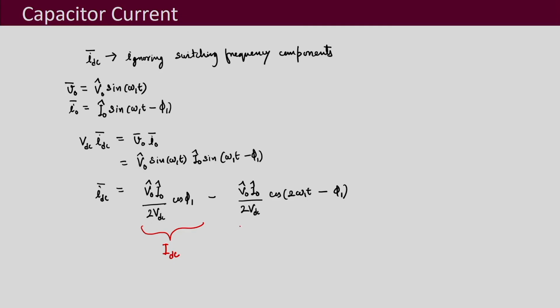Usually what we will expect is that it is a DC bus current, meaning it should be a flat DC, but we have seen that a flat DC is not what flows through the DC bus. It has a switching frequency ripple, which we have ignored. So then definitely it should be only the DC component. That of course we are seeing, but there is something else to it, and this is varying with a frequency twice the fundamental. So, this is the second harmonic of omega 1.